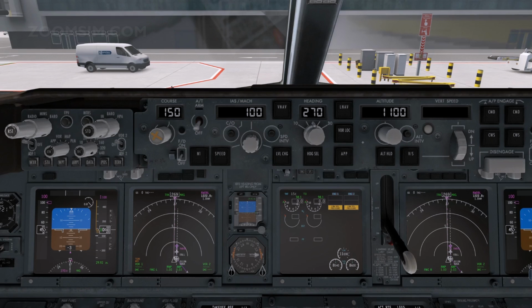In the approach position, the following information is displayed: localizer and glide slope information, reference ILS receiver, ILS frequency, course, and DME, and GLS receiver, channel, course, and distance. Weather radar and TCAS are not displayed in center approach mode.